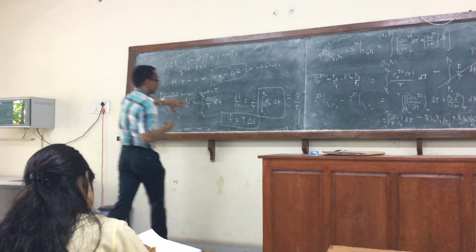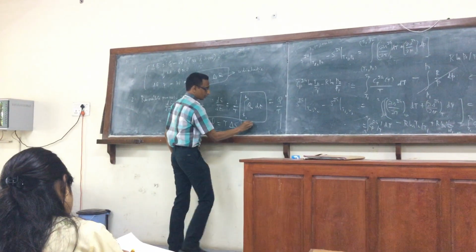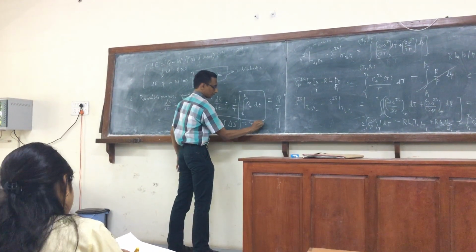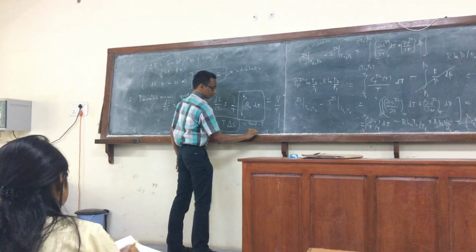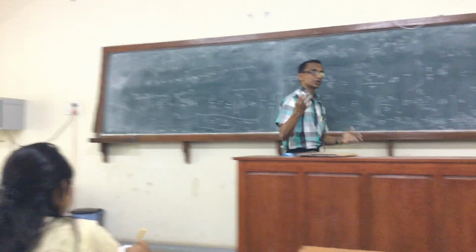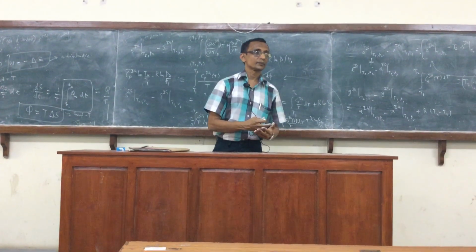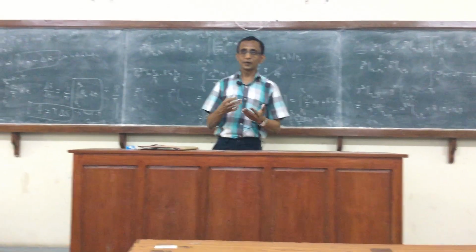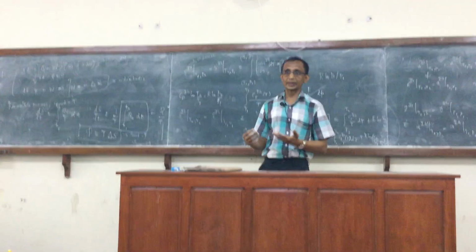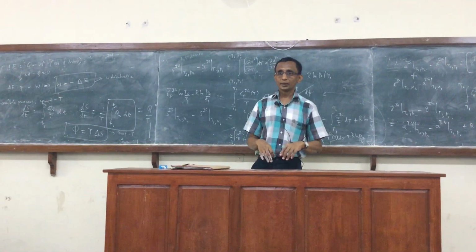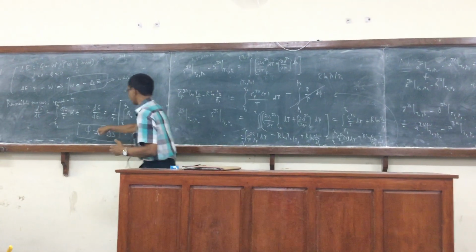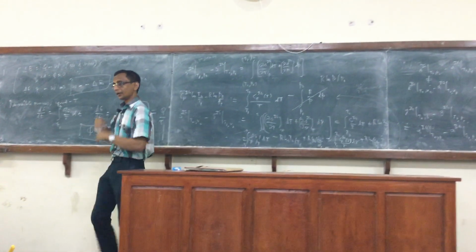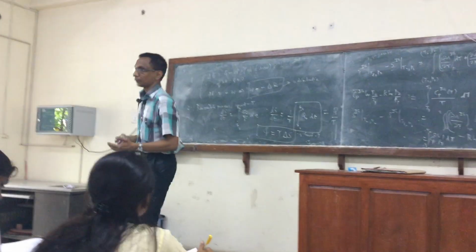Now here though, the qualifications are constant temperature plus reversible. Then the change in entropy will give the net heat absorbed or emitted, whatever the heat interaction is, since the heat is given by the temperature times the change in entropy.